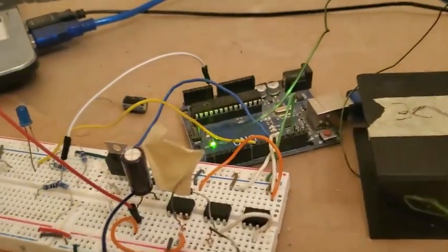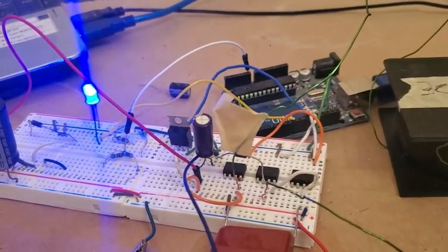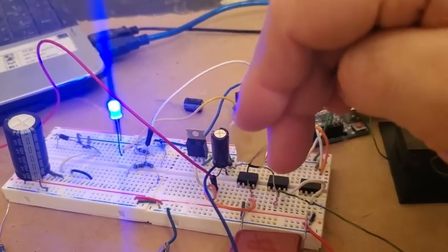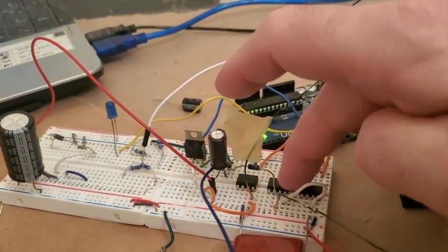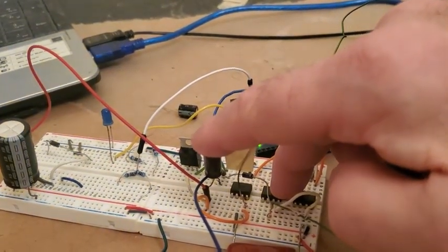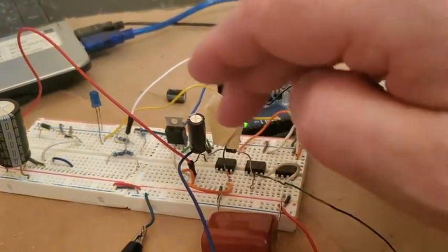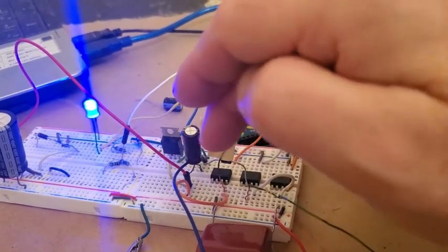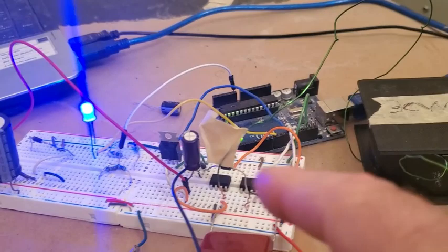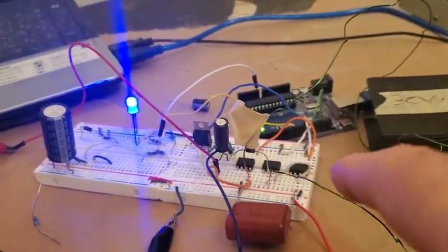Unfortunately, I can't go over 30 volts with this setup. These SSRs are rated for 60 volts, and I kept going up to 50 volts, and I fried a couple of them. And then it finally occurred to me, this is a buck boost configuration. So when this one here goes to discharge into here, let's say you charge this one to 50 volts. It had 50 volts here, so this is actually negative 50, this is 50. It's seeing 100 volts, and that's why they were frying. So I can go up to 30 volts with this setup. So I'm looking at it between 10 and 30 volts.